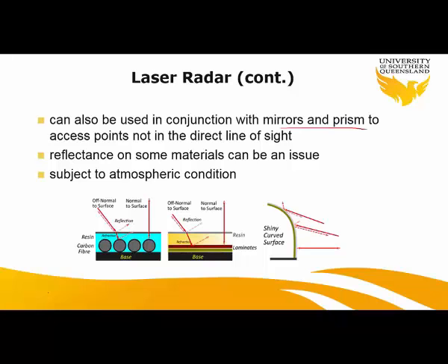We also have the disadvantages of laser radar. It's pretty much like laser scanning. It can be affected by the material that you're using. Reflectiveness of the material is important, same as other techniques. Atmospheric condition also affects the laser radar, so you can't really use the laser radar in every environment.